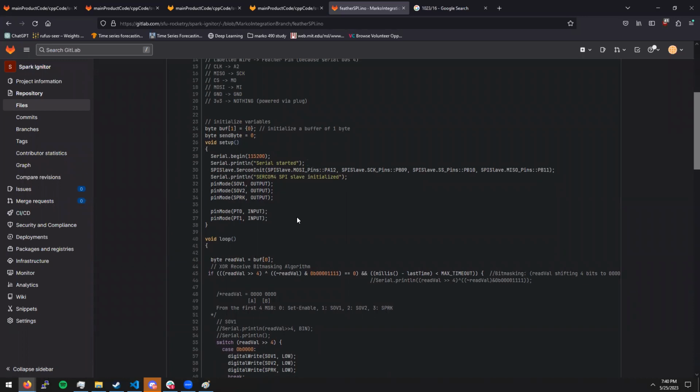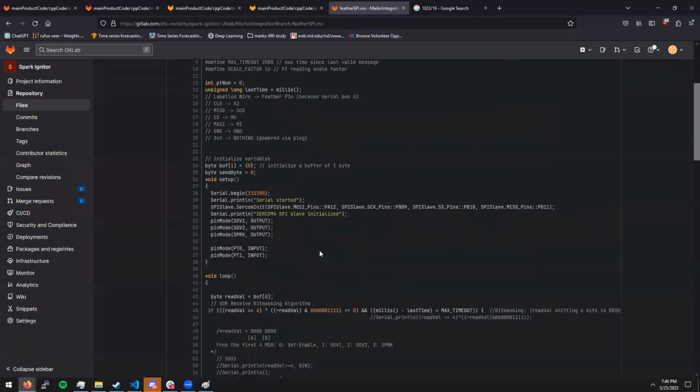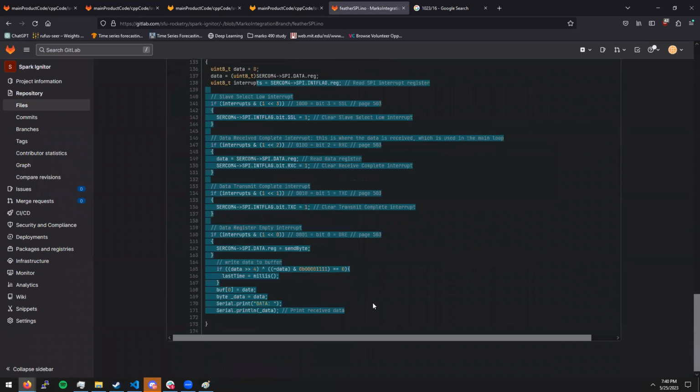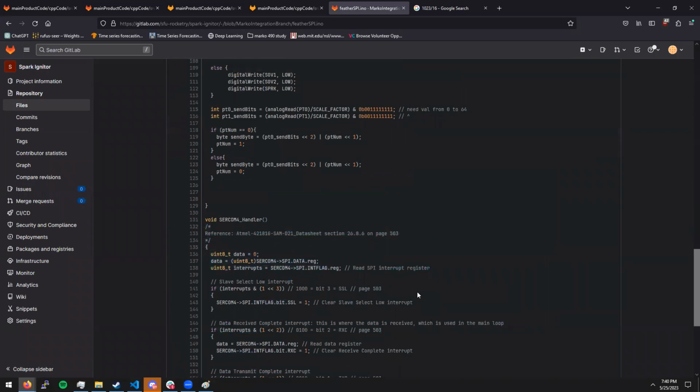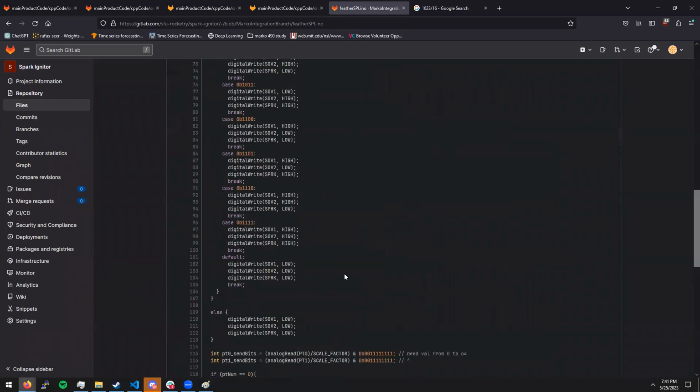The way the Arduino hardware was built, it doesn't support multiple byte transactions. You can do it, but it's kind of hacky and it's not 100% consistent. That's why I wanted to avoid it, especially as an SPI slave. But the Feather should have hardware buffers where it can store multiple bytes in a single transaction. So you'll have to update the code to allow it to do that, I think. But I don't think it'll be hugely complex. That's something I think G and Travis could probably handle.